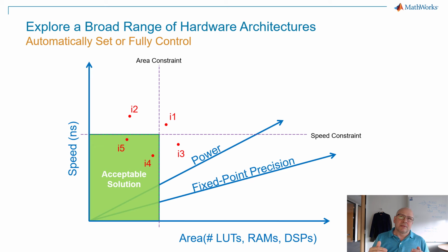Well, yeah, you'll get the direct magnitude in that case if you take the square root of the sum of squares, but do you really need to? You don't have to be a PhD in math to know that they're going to be the same ordering whether you're looking at the square root or the square itself. So in that case, if the algorithm developer specified a square root, and the hardware designer is disconnected from that process, you might still do the square root, but if they're consulting with each other, you don't need to do that. You can just use the square.